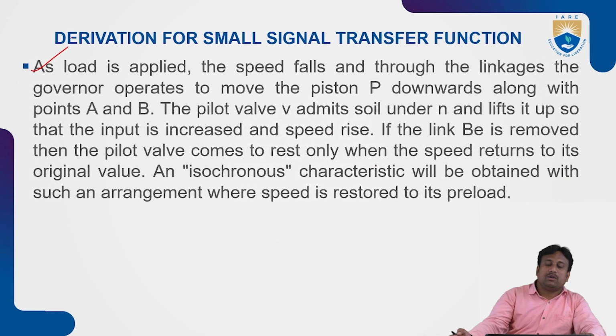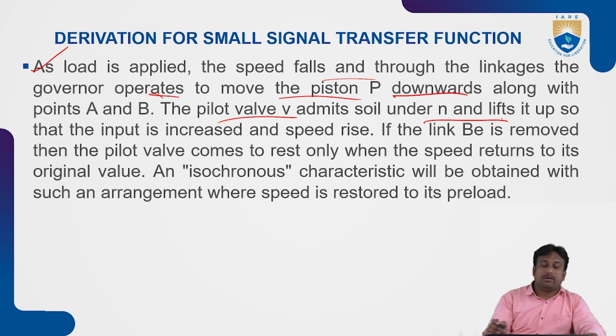So here, as the load is applied, the speed falls, and through the linkages the governor is ready to operate to move the piston P downwards along with the points A and B. So pilot valve V admits oil under pressure and lifts it up so that input is increased and speed rises.